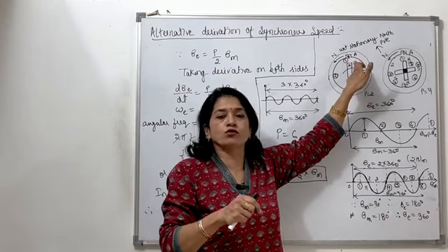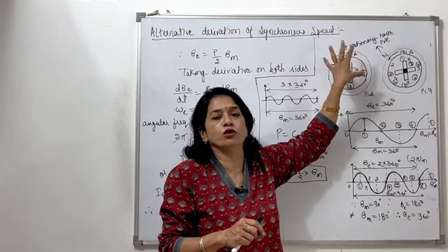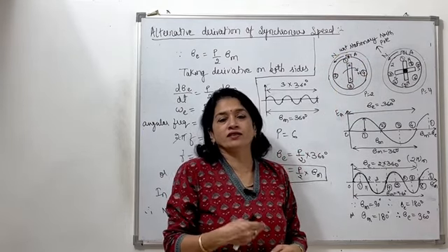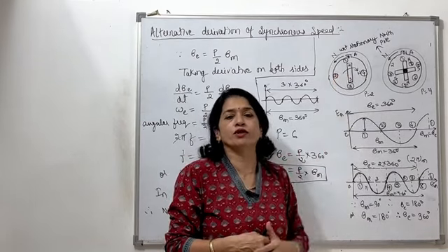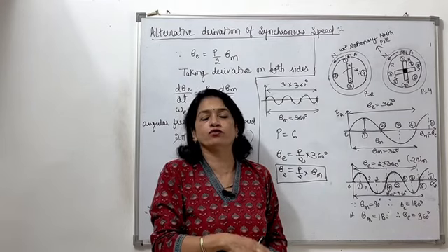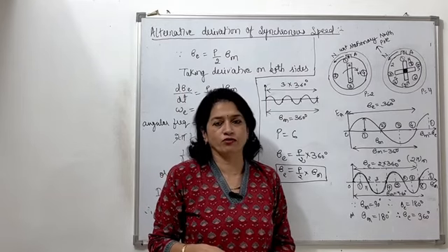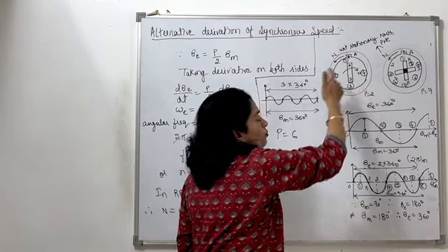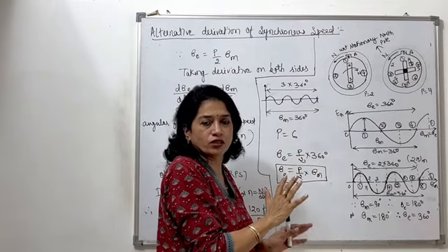Why am I assuming this? I want to know the magnitude as well as the direction of the EMF induced in this conductor due to the cutting of the flux, through Fleming's right hand rule, and that rule says the conductor itself should be in a moving condition. So relatively I am showing the motion of the conductor in the anti-clockwise direction so that I can apply Fleming's right hand rule to find the EMF's direction, and later utilize it to find the magnitude of EMF also. As the conductor is moving anti-clockwise, the poles are stationary, and the rotor has zero rotational speed.